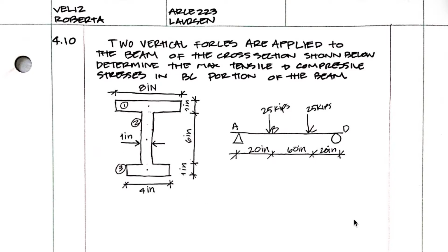So we know that we're going to be looking for a centroid. The centroid is going to be closer to this top, heavier part of the beam, because that's where our neutral axis is going to be located in a section that's obviously not in the center, because it's top heavy. So we're going to do a centroid calculation, and I'm going to pick a point based off of the bottom, just because it's natural to have a positive y going up and a negative y as our y bar for our dimensions.